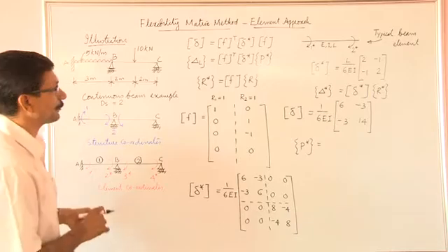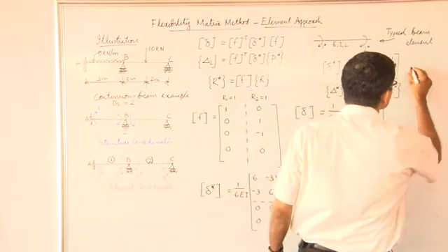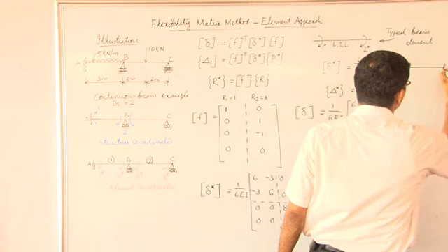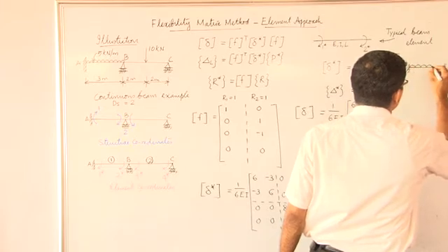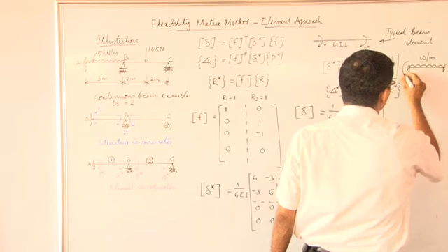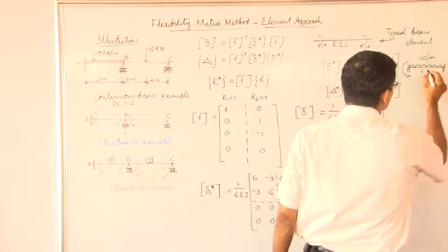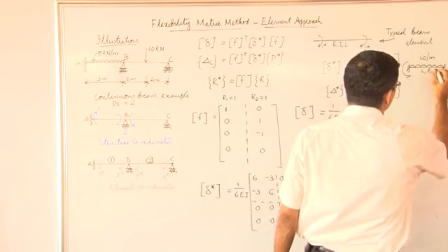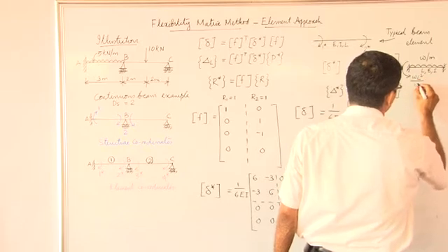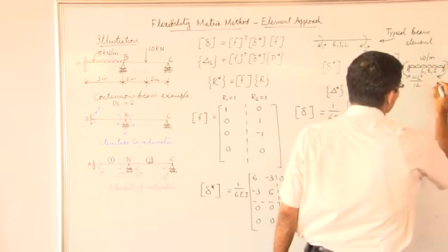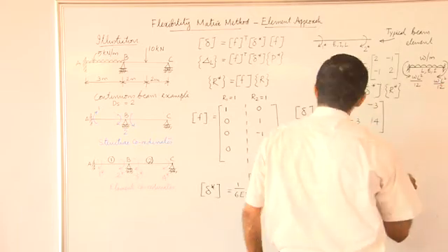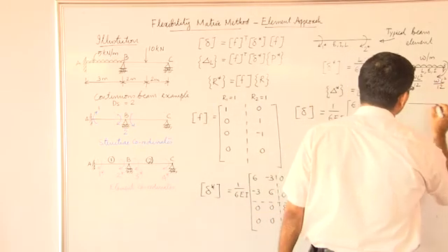So the number here would be, if it is W per meter, the fixed moment here, of course, span is L, we have E, I as the properties. This is W L square by 12. This moment is also equal to W L square by 12. We follow that. And for a point load,